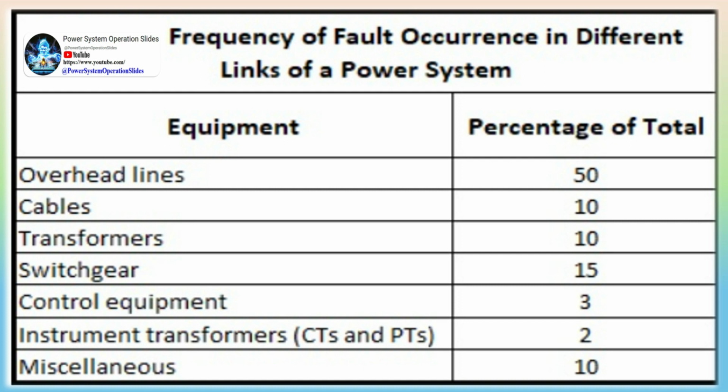Smoke of fires. Ionization of air, due to smoke particles surrounding the overhead lines, results in spark between the lines or between conductors to the insulator. This flashover causes insulators to lose their insulating capacity due to high voltages.